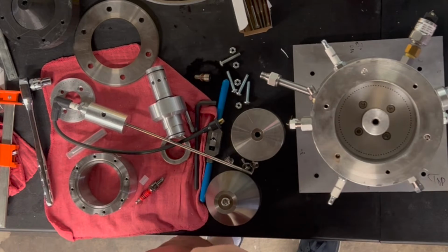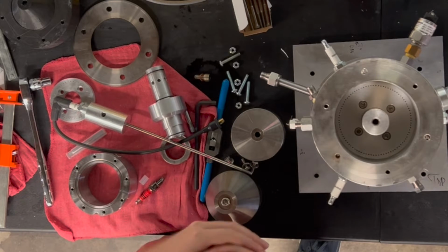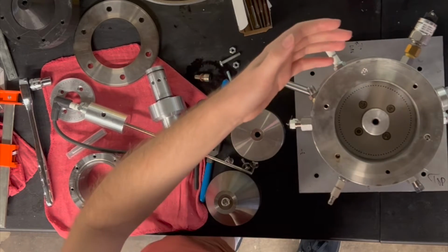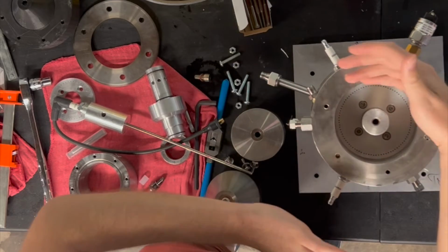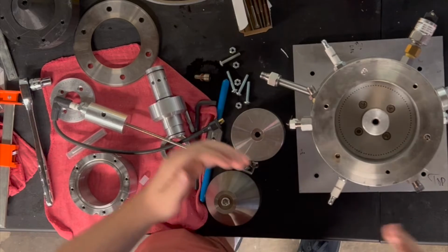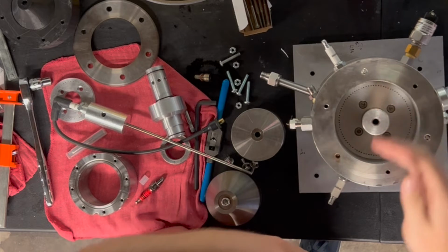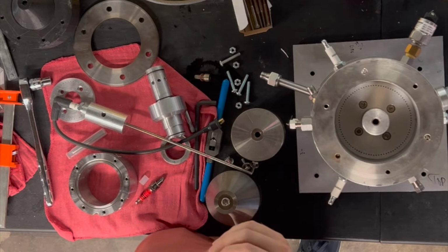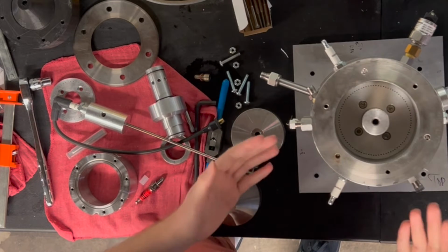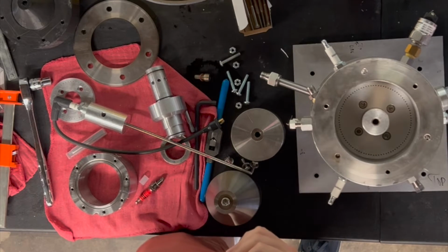Now, the detonation wave produces a very high efficiency combustion, but also introduces some challenges that we're here to work with. So the main challenge is that the detonation wave is highly transient and it spins around the chamber. When it exits the chamber, that means that apart from the axial flow that you would expect from a rocket engine, you also get a pretty significant tangential flow that can lead to a loss of efficiency in a normal engine nozzle. So one of the main goals of a nozzle specifically designed for a rotating detonation engine is to correct that tangential flow and get it straightened up to go axial again.